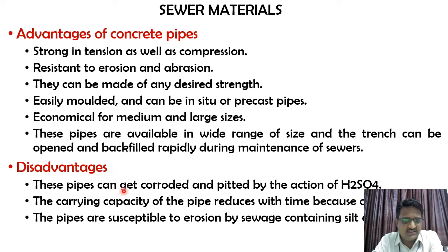Disadvantages: these pipes can get corroded and pitted by the action of H2SO4. One major issue here is that since we have reinforcement, over a period of time, if the reinforcements get exposed to the sewage, the acid formed during the flow of that sewage can affect the reinforcement and ultimately corrode it.